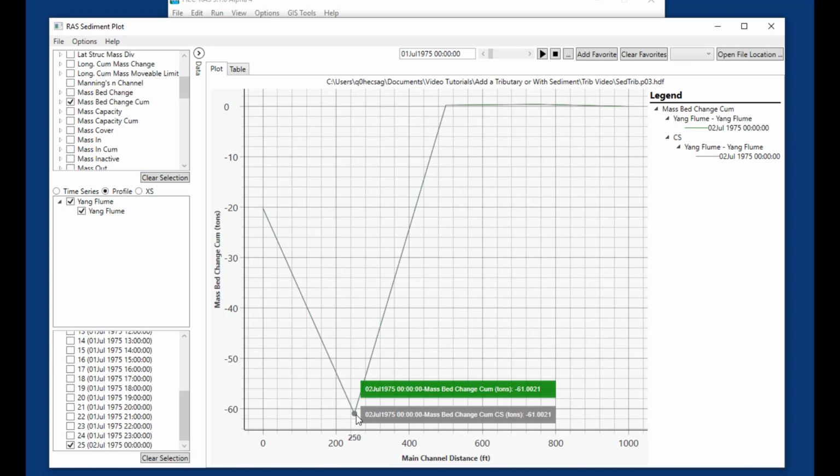because we've brought the flow in without bringing any sediment. So we've increased the capacity over this equilibrium state, but we haven't given it any sediment to fulfill that capacity, and so it erodes downstream of a tributary. This is actually something that happens in the real world and something that happens numerically. It's a common numerical artifact.